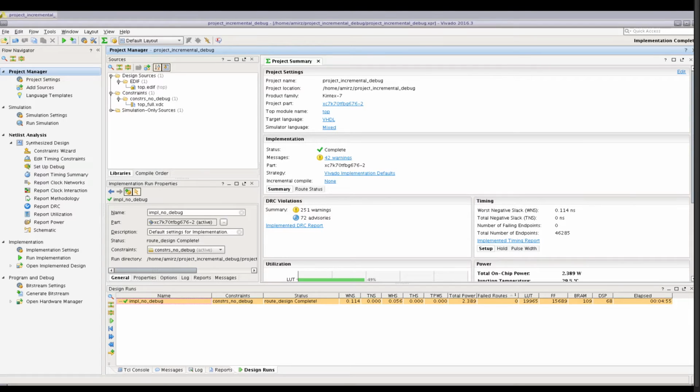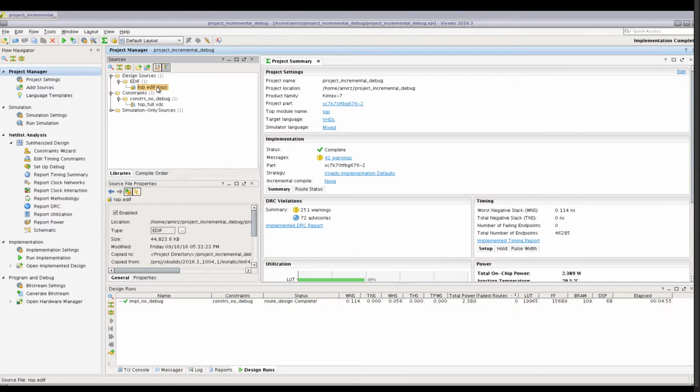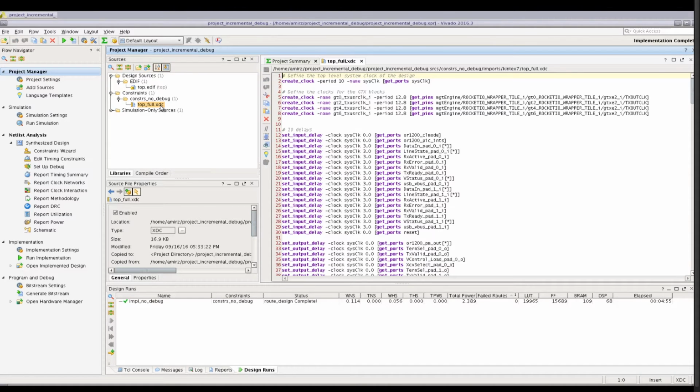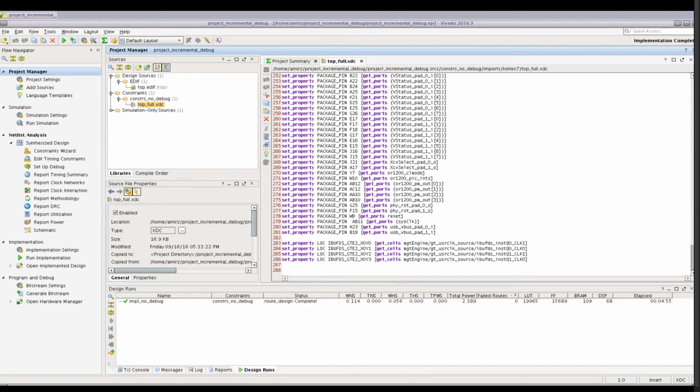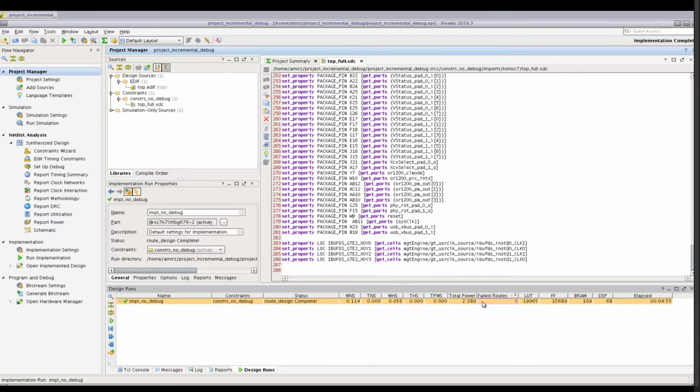The example design we use here is a netlist-based project. It has a synthesized design as a source file along with a constraint file. The constraint file only contains the timing and physical constraints and has no debug information in it. This design has been implemented in project mode using the GUI with default flow, which is non-incremental. As you know, project mode generates and stores implementation results and supports the creation of multiple runs to configure and explore available constraint or command options.